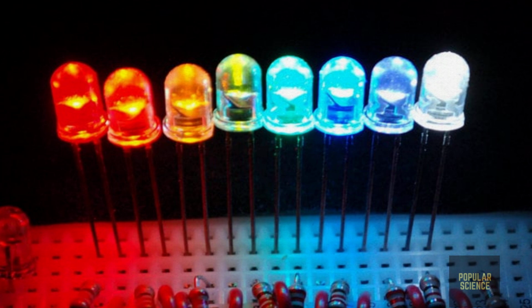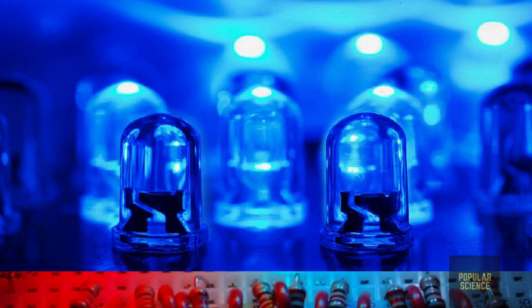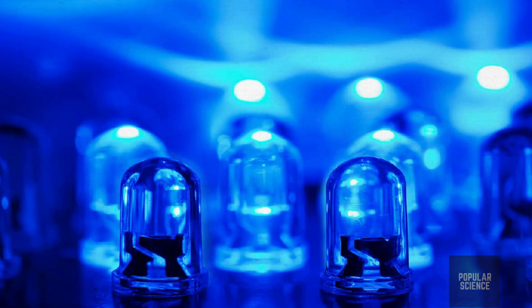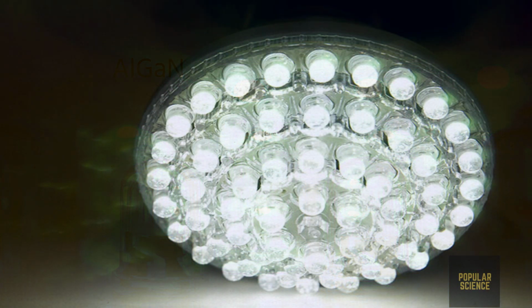According to the famous E=hν formula, we can calculate the color of the emitted light. Different PN diodes have different values of band gap, so by changing the band gap, we can produce different colors of LED. Like blue LEDs are produced by aluminum gallium nitride semiconductor and green LEDs are produced by indium gallium nitride semiconductors. White LEDs can be produced in two popular ways.